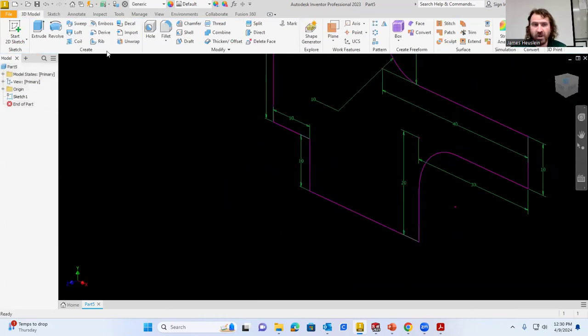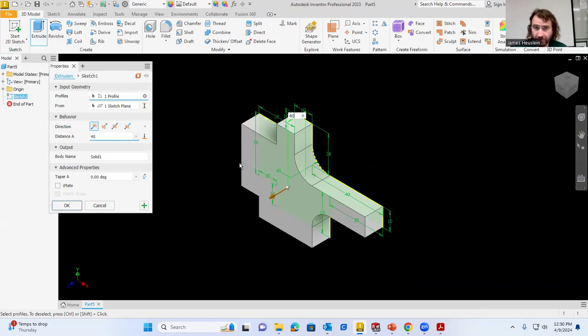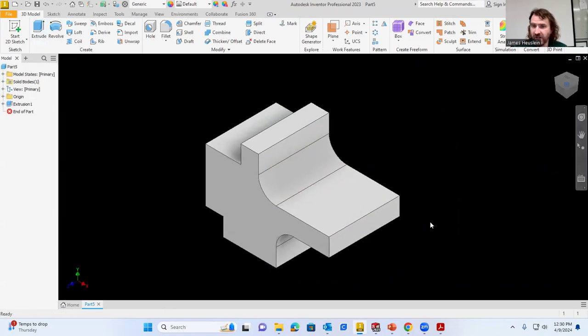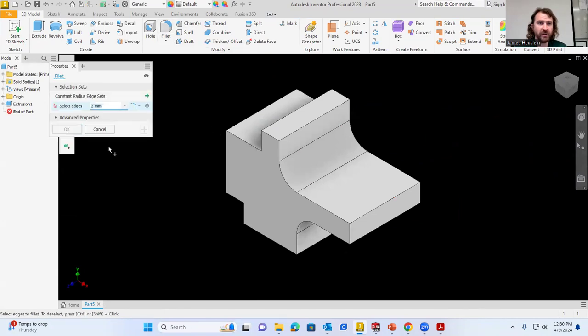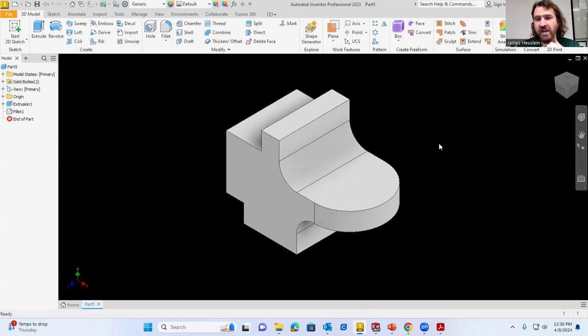Finishing the sketch. Again, this extrusion was supposed to be 40. There it is. And now for the final touch, the fillet tool. Again, it's a 20 millimeter fillet this time, and we're clicking on the edges that are going away. Right? Those edges that are being filleted, material is being removed from them, and filleting that edge. And that is 20. And there it is. That is the interesting lesson 21 that's part of this packet.